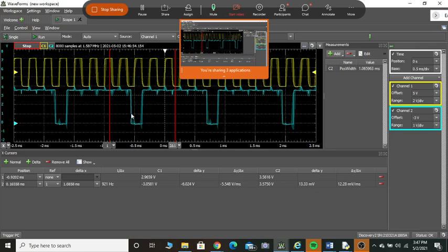Can you see this has ended the quasi-stable state? Now here you are getting the next trigger signal during the stable state condition. It goes to quasi-stable state, and remains so. Can you see whatever the frequency of your input signal is, the width remains the same, constant? Does the width remain constant now? Is it almost 1 point something millisecond? Almost 1 millisecond.